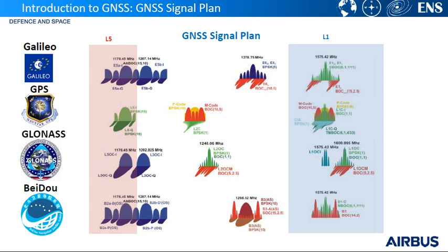There are currently 4 GNSS constellations: GPS, developed by USA, GLONASS, developed by Russia, Beidou, developed by China, and Galileo, developed by Europe. They are complemented by several regional GNSS and augmentation systems. The GNSS satellites continuously transmit navigation signals in 2 or more frequencies in L-band. Signals which are currently used by mass-market devices are L1 and L5.